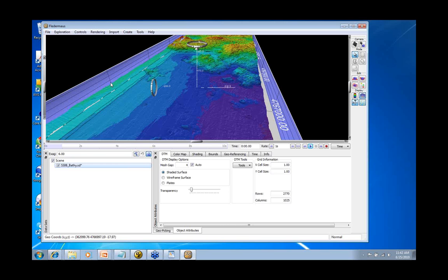When we went to the georeferencing tab, because we're kind of doing it along with you guys with our own data, the coordinate system changed back to the default, even though we had entered a different coordinate system. Are you sure for the output coordinate system that you changed it?